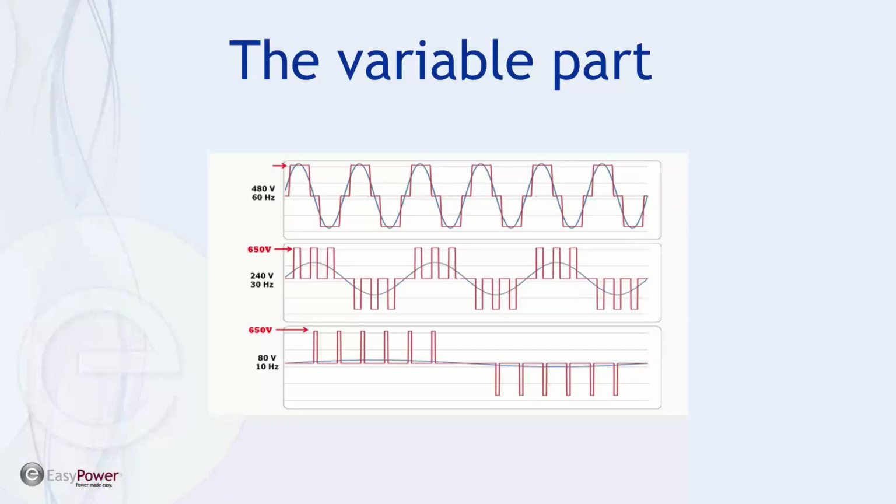One of the benefits of a VFD is the ability to improve the power factor the system sees from any given load, and that's relatively simple at the home frequency, if you will, of the motor itself and of the drive system. This becomes more complicated when we have a different frequency, and some of that is what's going to complicate the discussion going forward.